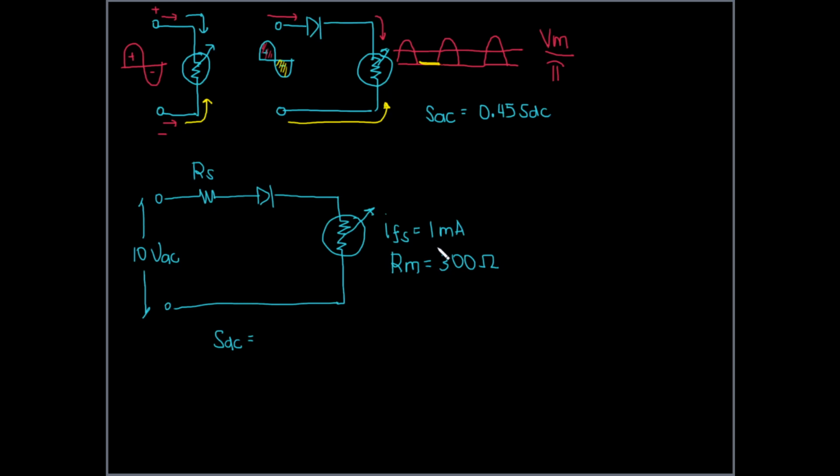And remember also that sensitivity is the reciprocal of your full scale current. So if your full scale current is in DC, then you are only capable of determining first your DC sensitivity and not the AC sensitivity.